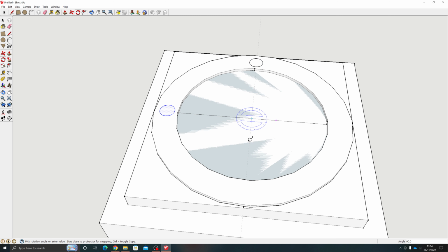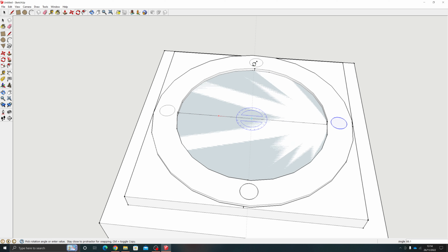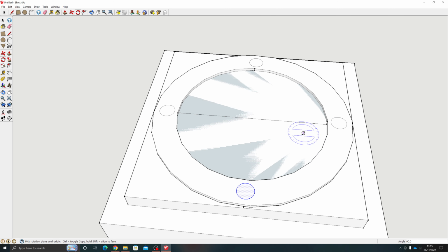If you tap that, it copies at the same time, so you can actually rotate an object round whilst copying it. It means I can make sure that the same component is equally spaced. You can type the measurements if you want to, so we're changing it by 90 degrees each time. So you could type 90. For mine, I can see it in the bottom right here. When I get to the right position, it's 90 anyway, because I line it up with each of them. And it does naturally lock onto 90, because they quite like getting to the correct degrees.